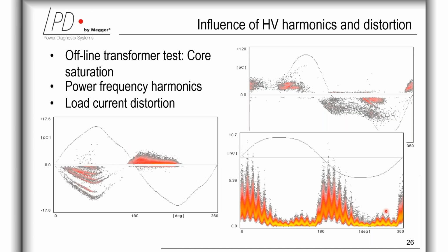And the third pattern here is showing a PD pattern of voids in a polymeric material with a semiconductive interface. The applied voltage here has a content of the third harmonic, and for this reason, it's causing this almost triangular shape of the voltage. Discharges of spherical voids under a low rate of charge carrier generation directly reflect the electric field and show the wave shape and its distortions one-to-one.